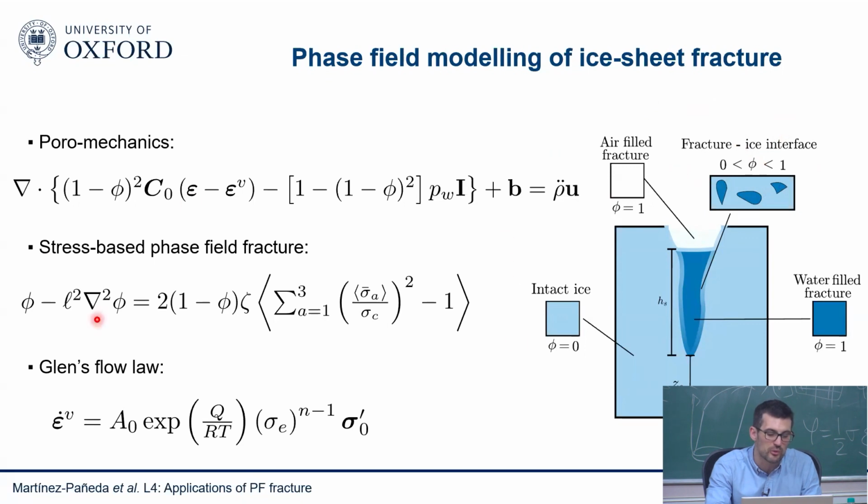And then basically we change a little bit the phase field fracture model. I told you before there were multiple models, AT1, AT2, phase field cohesive zone. This is one of those models, more like the phase field cohesive zone. So it's based on a critical stress. I actually like the conventional one very much because it's based on Griffith. The reason why we use this one is that it separates a little bit the length scale from the fracture properties.